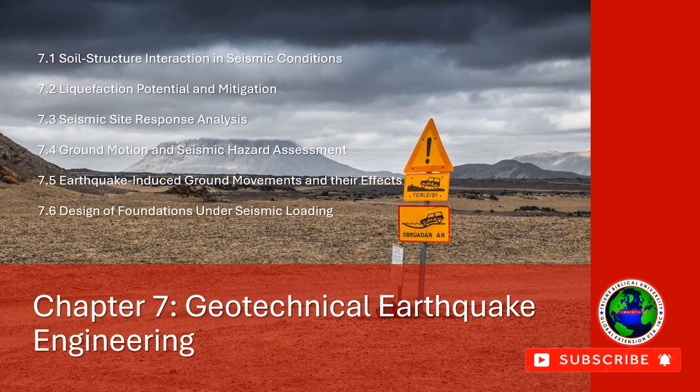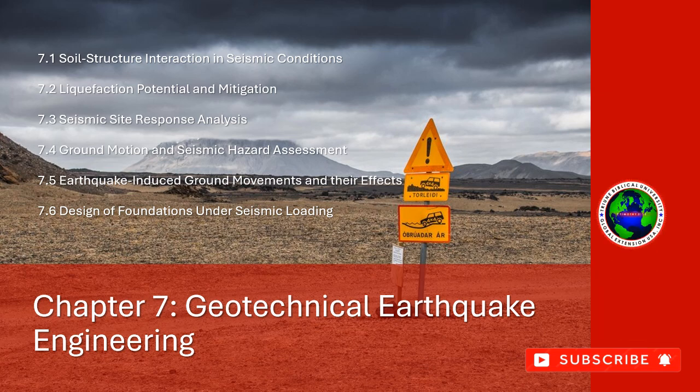Boundary element methods, BEM. In some cases, boundary element methods are used to model large-scale soil-structure interaction problems, particularly for very large structures, as they reduce the computational load compared to traditional finite element analysis.